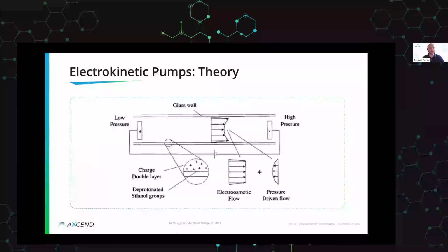So next on our list is electrokinetic, or sometimes known as electroosmotic pumps. So similar to the theory of capillary electrophoresis, when you have a buffer system, you'll generate a charged layer around the walls where ions start to migrate. If you then apply an electric field to that, the ions will migrate toward their respective poles, so going toward the negative or the positive. And as those ions migrate, based on the electric field applied, they drag the bulk of solution along with them. And so by doing this, you can generate a flow of bulk solution based on only that little bit of